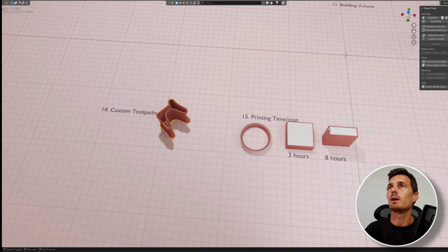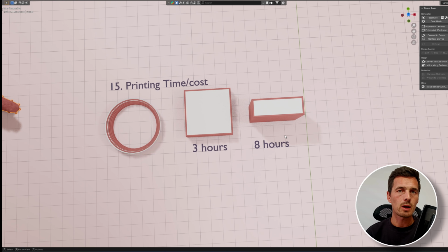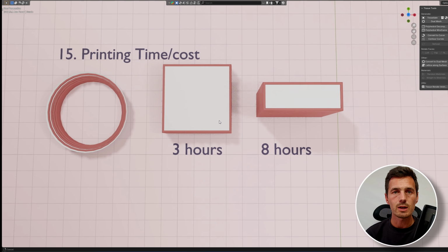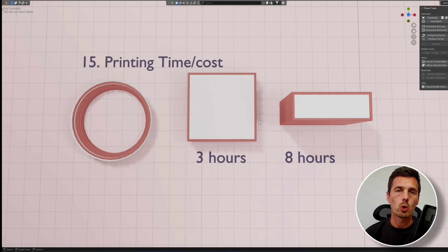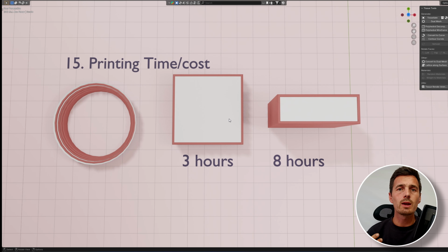If we are talking about cost, an important factor for the cost is printing time. So as we saw in the heat control section, we always take more or less 1 minute per printing layer. This is different per setup, but most of the time you are tuning your printing layer to print for a certain amount of time. So printing time and cost are related to each other.